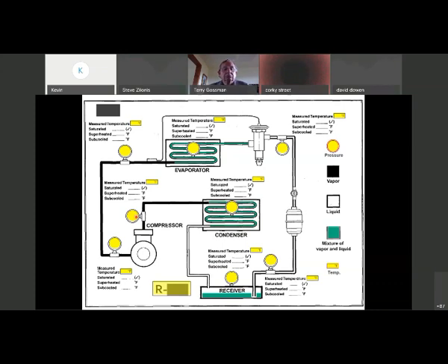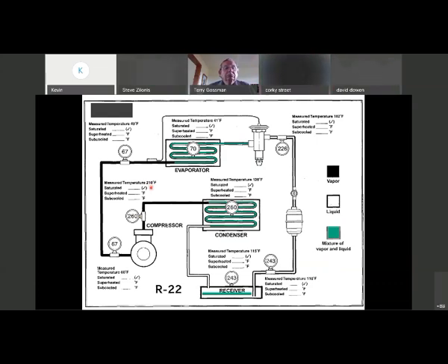And every one of these gauges has a poundage attached to it. We'll just change that over so it has the poundage. And we'll take some readings on this and see what's going on. It has a measured temperature, so you can actually see what's going on as far as the temperature is concerned, and see where there's subcooling. You can see where there's superheat. You can see saturation, that kind of thing, because these numbers applied against the data.